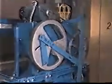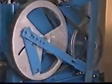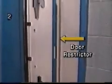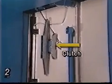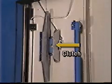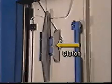The doors on the elevator are called car doors or gates. The door operator is a machine mounted on the car top. This machine opens and closes the car doors. The door restrictor is a mechanical device that prevents the car door from opening when the car is more than 18 inches from a floor. The clutch is a device mounted on the car door, which engages the hoistway door pickup rollers and actuates the interlock, causing both sets of doors to move together.